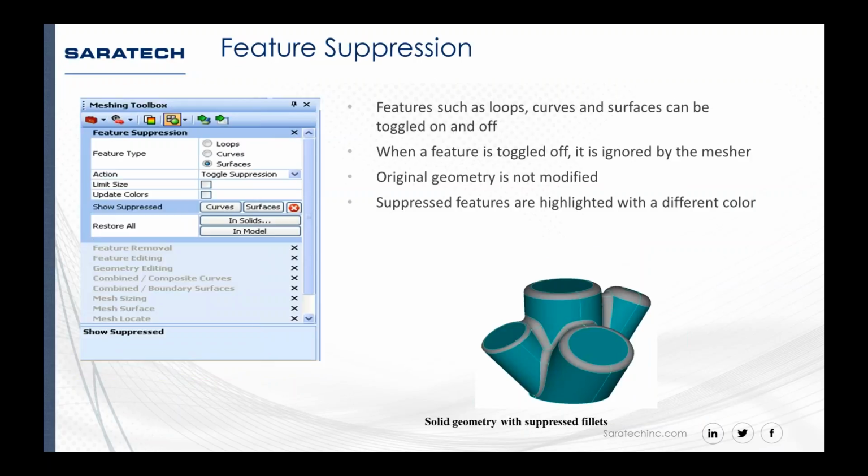The next command down is feature suppression. Basically we're taking our structure and suppressing some sort of entity. I'll just say fake deleting it. We're not modifying the geometry, but we're hiding it from the mesher. If we were to mesh this structure as we see now, those gray arrows are suppressed at this moment, so the mesher would ignore them.